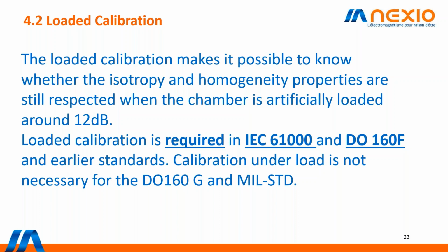The goal is not to load the chamber exactly at 12 dB. This value will change with the frequency and positions, but the goal is to load enough so that the Q factor will be lower, and then the E field will be uniform in the volume.